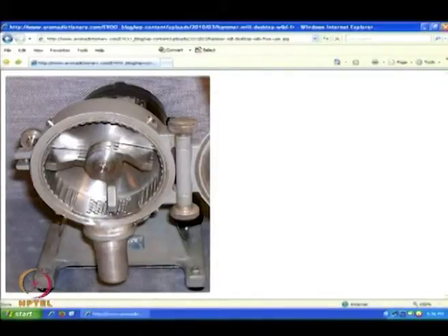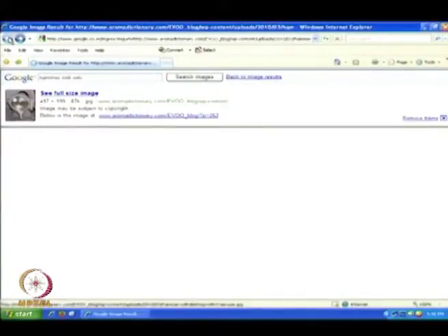Now, if you feed material from the top, as this whole rotor arm is rotating, these vanes are also rotating. So, as you have fed your material from the top, what will happen? As these rotate, all this material which is contained over here would be crushed at these spaces, and here what you have is a powder, finer powder gets out through here. This is one variation of hammer mill.